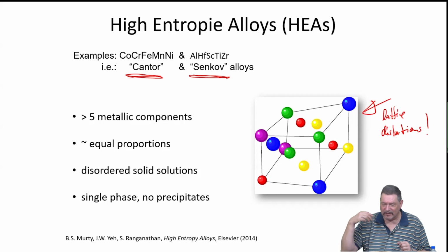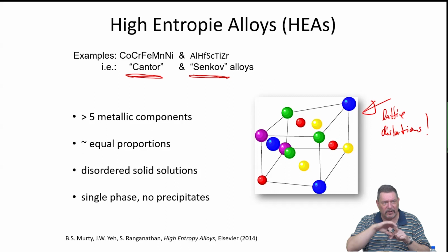And so it means that sluggish diffusion and all these other things can basically be broken down to lattice distortions, to just the ability to build up a common host lattice and put all these different elements close to each other at random at the defined lattice positions. And then all of it will follow from there. So it's not really 4 key properties of high entropy systems.